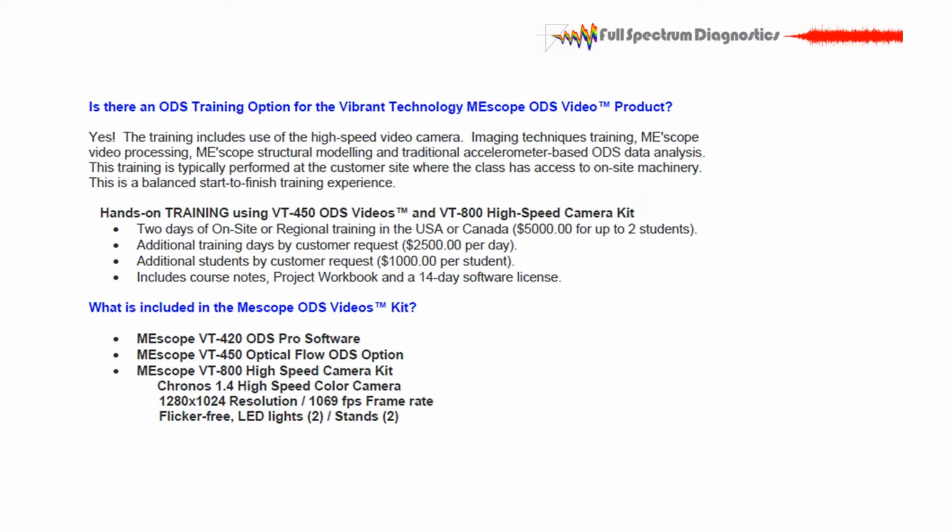I've been doing a lot of videos, and it doesn't take long to take the data in the field. It's more setting up the lights, making sure everything's right, everything's steady, and you take 1 second worth of data and you're done. And you go do another view. So I usually, on any machine of interest, I might take a dozen videos or so and look at the foundations, look at the motor feet, look at any interface, take an overall shot from multiple directions, and make sure I've mapped it pretty good.